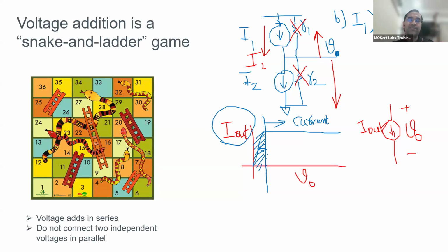Okay, could be a bit confusing right now, but just for now, go with this assumption saying only finally one current will flow, which is the smaller of the both, but the voltage will be pulled towards the top side. And this is a good experiment to do in your lab. Whenever you do this, or even in simulations, you can pick some simulator and try it. Basically, the arm wrestling will happen. The stronger current source will pull it towards that. If the high side current source is stronger in magnitude, the output voltage will go up. If the bottom side current source is strong, then it will keep pulling down. That is what will happen.